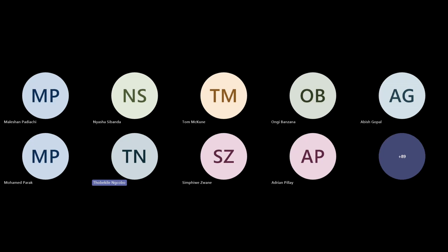So the original cover, as per the as-built, was 40 millimeters. However, we did observe on site that other areas had low cover, obviously due to the construction deviations. Second part of your question, the fire didn't have a significant effect on the steel itself.